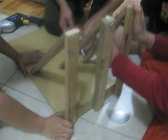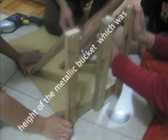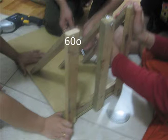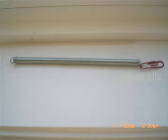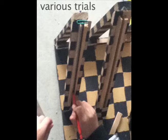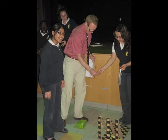The spring flinger was built keeping in mind various measurements such as the height of the metallic bucket, which was 37 cm high. Three different ramps were made with angles 60 degrees, 55 degrees, and 50 degrees to the horizontal. A paper clip was attached to the end of the spring so that it was easier to release. The spring was stretched to an x value and released so it hit the bucket. The constant for the spring was calculated to be 15.3 newtons per meter after various trials with the spring.